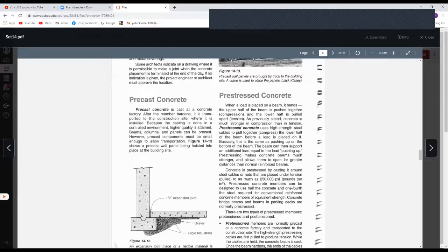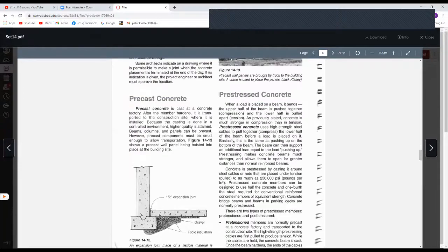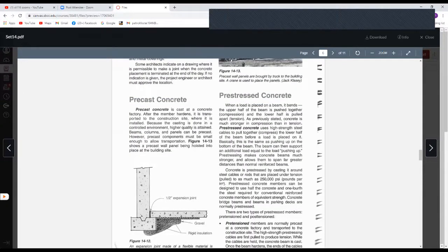Yeah, I think they had expansion joints, and then when they started getting conscious of the importance of insulation, somebody said, "Hey, can't we stick a half-inch piece of foam down there?" And somebody said, "Sure, why not?" Because it could still expand through that. It would just crush that foam. But yeah, they do that too, which would make it a non-monolithic pour. They might even pour the footing and then pour the wall, like a basement wall, into a key as a second pour, and then maybe even do the slab as a third pour if it didn't touch.